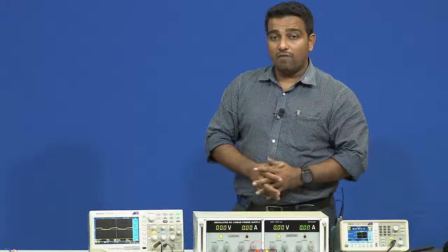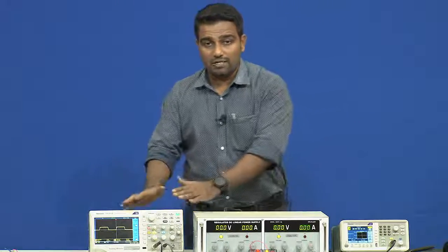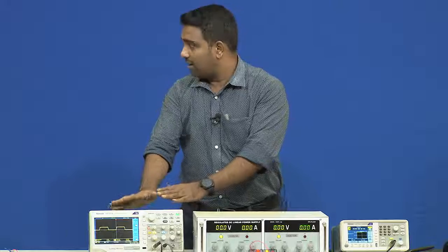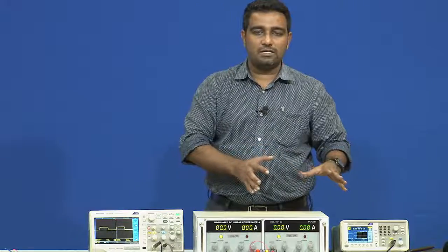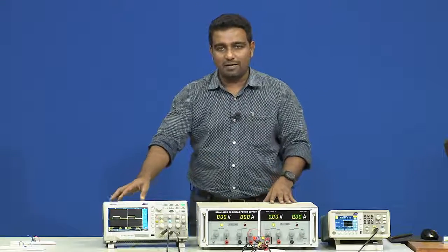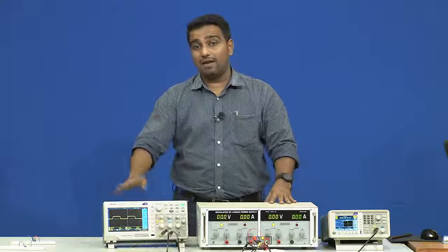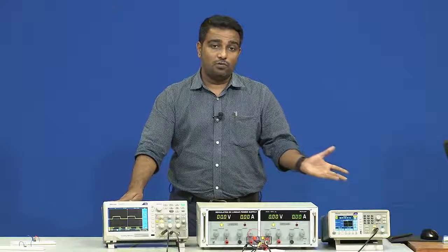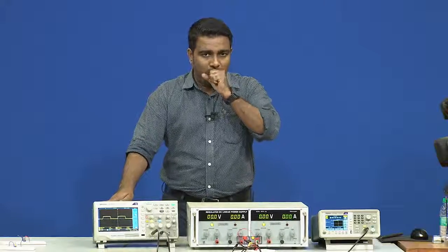Alright. So, now if we know the change in the voltage, which we can understand using the oscilloscope, and then we see the change in time, that is delta t. So, delta v by delta t will give us the slew rate. So, it is very easy.